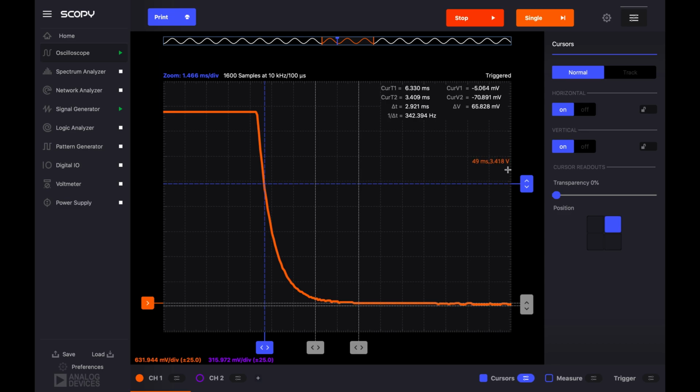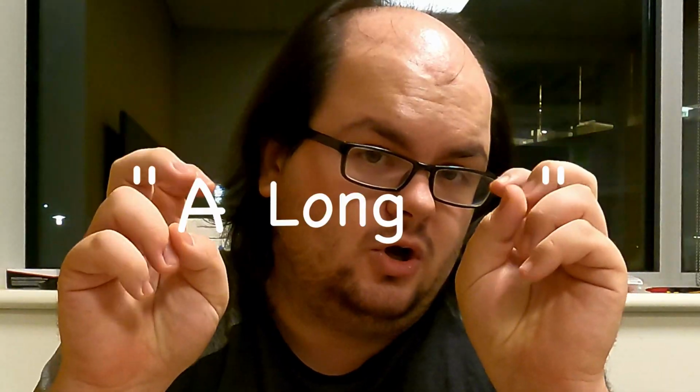So here's what I want to do. I need to find the time constant. I want to measure the time constant of the natural response. The time constant is when the capacitor voltage discharges by a factor of e from what it was originally at. We've held it at 5 volts for a long time at this part here, and then we said, okay, start discharging.